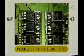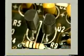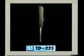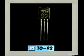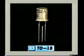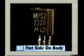Transistors are used for a large variety of purposes in electronic circuits and come in a wide range of through-hole and surface mount styles and sizes. Through-hole transistors usually have 3 or 4 radial leads. They are identified by their names, such as TO92, TO18, TO251, or TO220. The numbers are standardized in the industry and refer to the physical size of the transistor package. Installation direction is usually marked by a tab or flat sides on the body of the component.